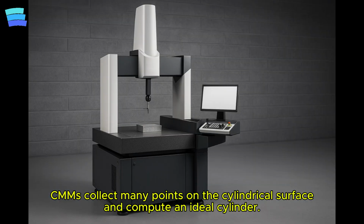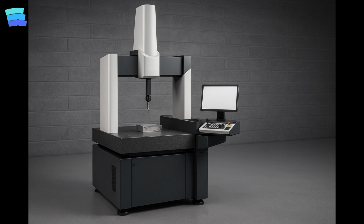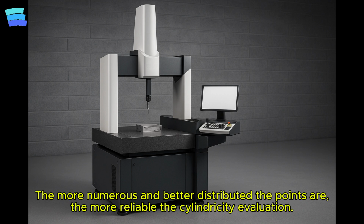Coordinate measuring machine (CMM). A large number of points are taken from the cylindrical surface. The software calculates an ideal cylinder and evaluates how much all points deviate from this model. In short, the more numerous and better distributed the measurement points are, the more reliable the cylindricity evaluation becomes.